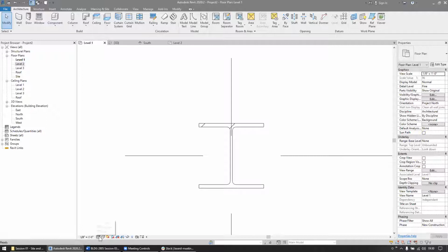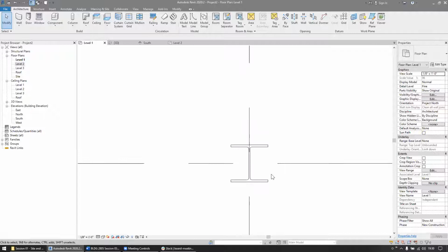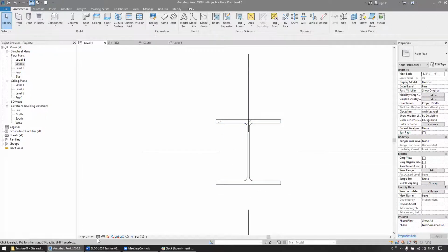Now, the one, of course, that's not 3D geometry, that's 2D geometry. But at the medium level of detail, Revit shows you one solid model that it has created without the fillets. And then at the fine level of detail, that's actually a totally different solid that's in there. And you're like, well, why couldn't they just add the fillets on there? I don't know. So just so you understand how these things are behaving. There's other structural objects that have the same thing where between medium and fine, they do show extra geometry once you make the switch between those different levels of detail.